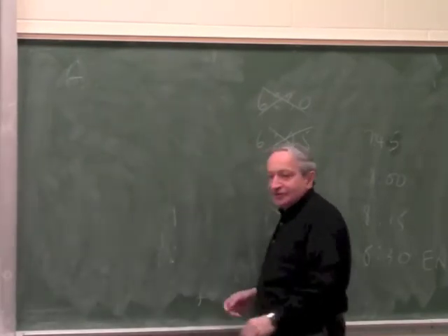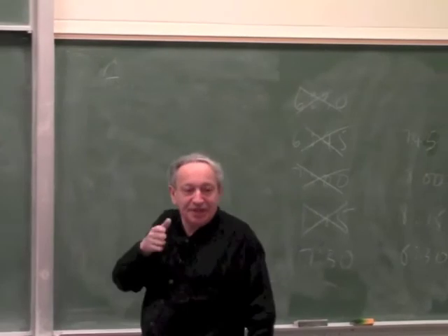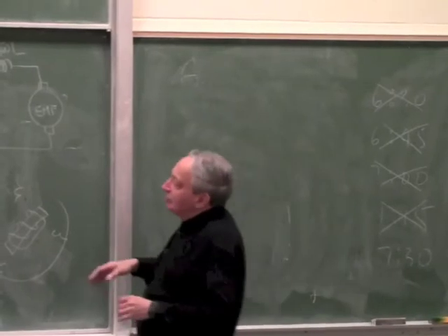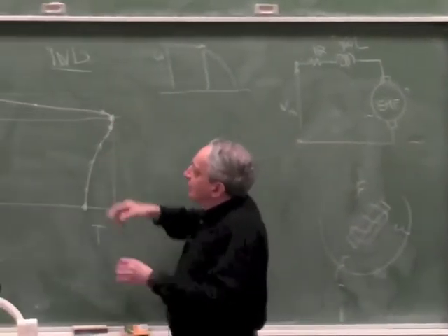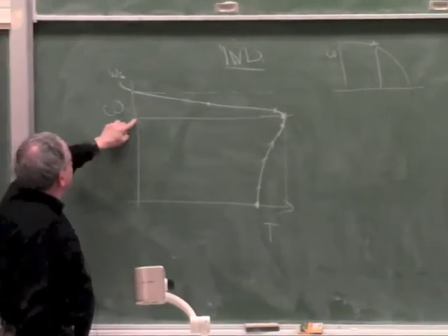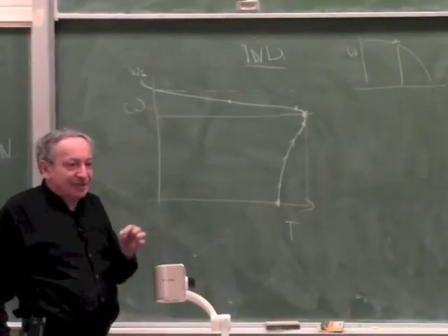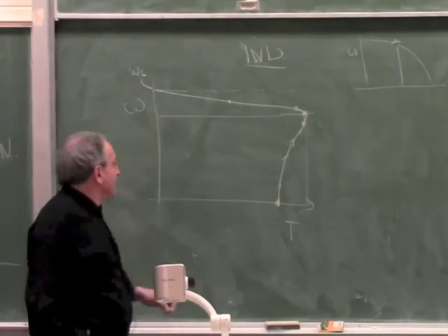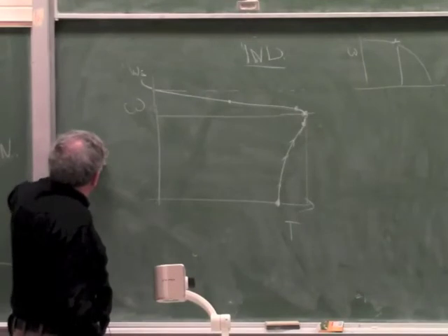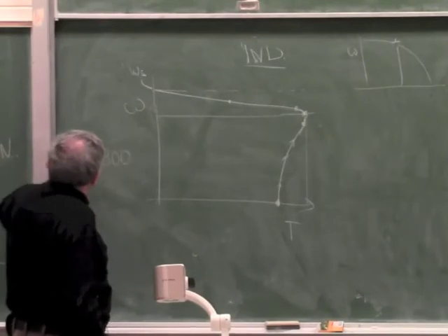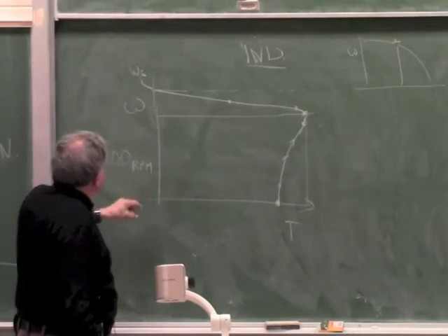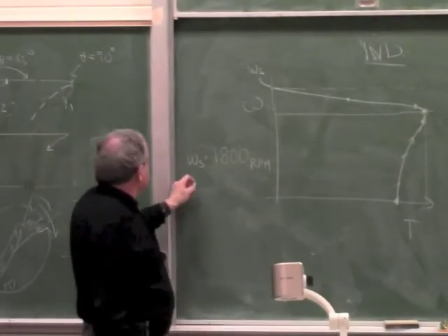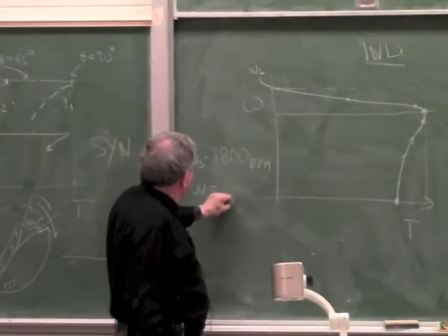Of course, there are other factors like the type of laminations, because again, there are hysteresis losses. There are many other factors. Altogether, it's optimized to work near omega S, and I gave you an example that it typically works 5% below omega S. If you want a better number, the typical motor in your home is 1800, omega S is 1800 RPM. I'm writing it in RPM, not radians per second, because that's what the motor nameplate says. And the actual omega this motor works at is 1725.